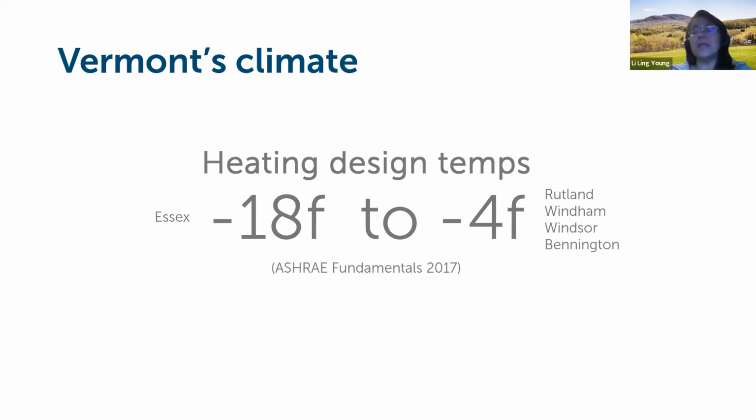So I'm not going to spend a lot of time on this, but the design temperature is the temperature you use to calculate the loads. It is not necessarily the coldest temperature the people in that place have ever seen. And that's really important to adhere to the way that the load calculations were built. If you think that you're doing a better job arriving at your load calculations by choosing a temperature that is not the actual design temperature, you're not. So I'd say this is just an ongoing issue that we see people who feel like they're doing the right thing by choosing a more aggressive design temperature, but that's not the way to do design. It is the way to plan your life, but in terms of design, use the design temperatures out of ASHRAE.